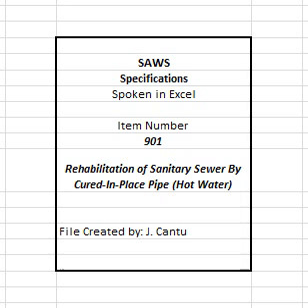Visual inspection of the CIPP shall be in accordance with ASTM F1743, Section 8.6, and Specification Item Number 866, Sewer Main Television Inspection. 901.7 Measurement. All sewer pipes will be measured from center of manhole to center of manhole or end of main.